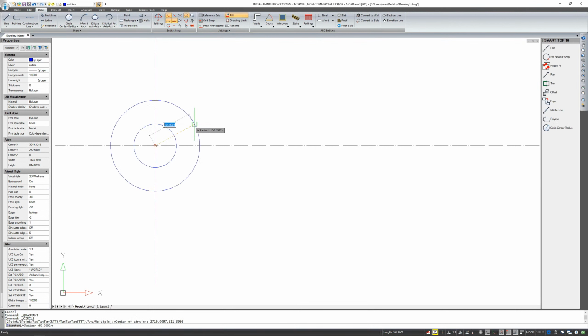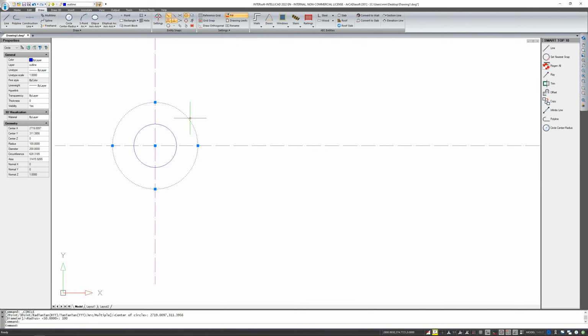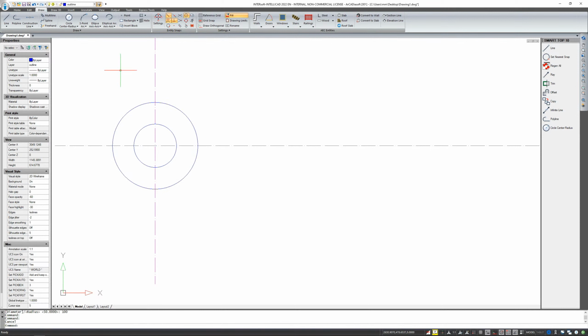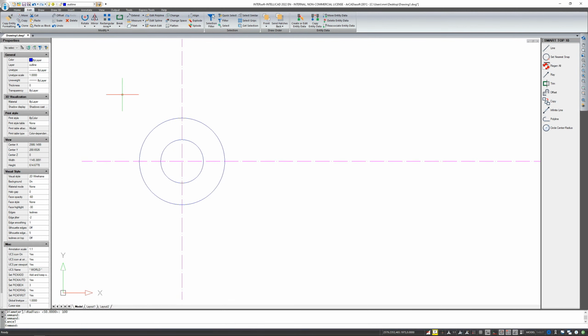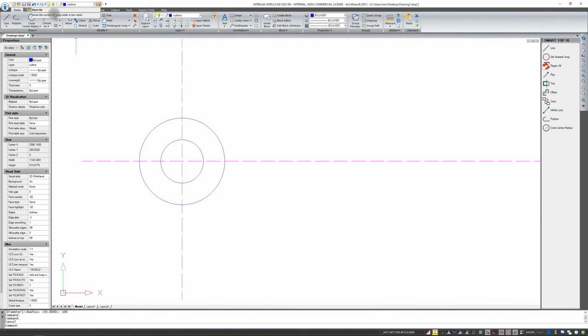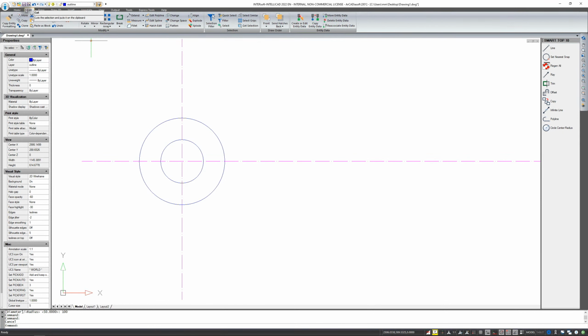Deleting an element, that is selecting this element and either selecting the delete option under the right button or simply the delete key on the keyboard. From the different options that I'll be using, I'll show you alternately one by one the drawing and editing options. Now I will draw an offset for this axis, which is an option that is on either the home ribbon, the offset, or the edit ribbon. It's exactly the same option. When I enable this option, I have to enter the distance, that is the distance between these elements. Here it will be 25 units. I confirm with enter, and now the selection.